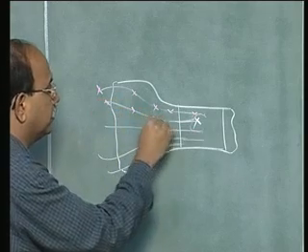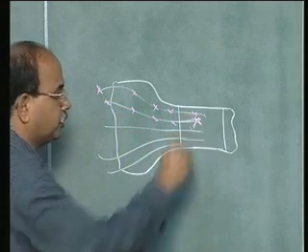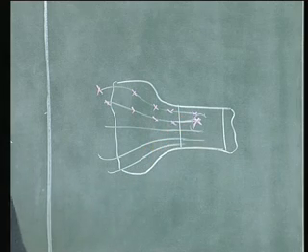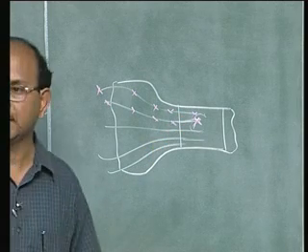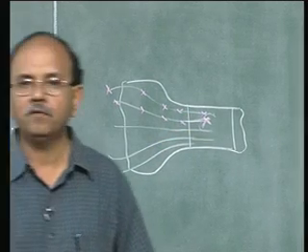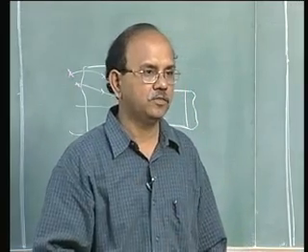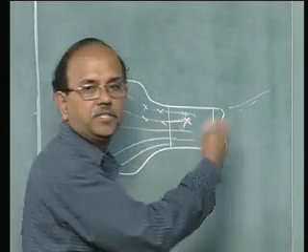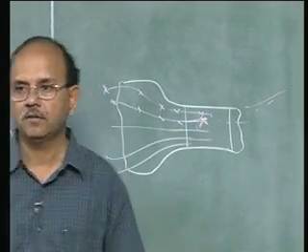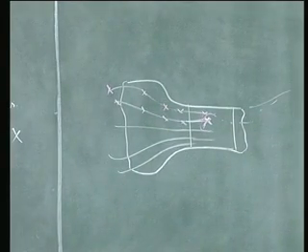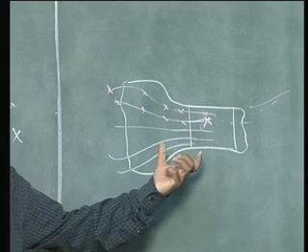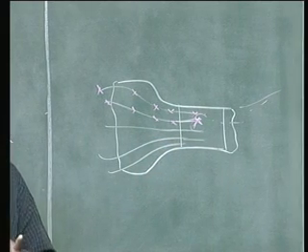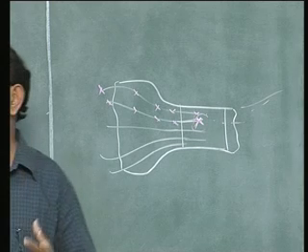This point may come here and come to this point, okay. So at that point it might have the velocity at a particular instant that you have noted. Further down it may go, there may be a change in shape, change in velocities and all these things, okay. So the first perspective, where you look at a point and watch what happens to that point, is an Eulerian perspective.